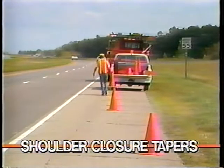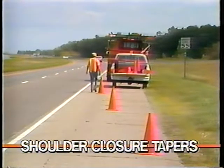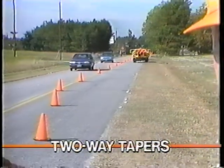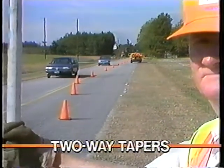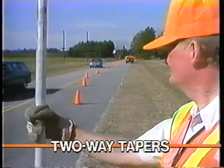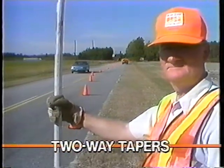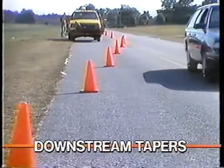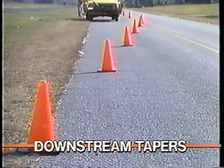Shoulder closure tapers are needed to close shoulder areas. Two-way tapers control two-way traffic, where drivers are required to alternately use a single lane. These tapers are used when flaggers are present. Downstream tapers are those installed to allow traffic back into the normal path.